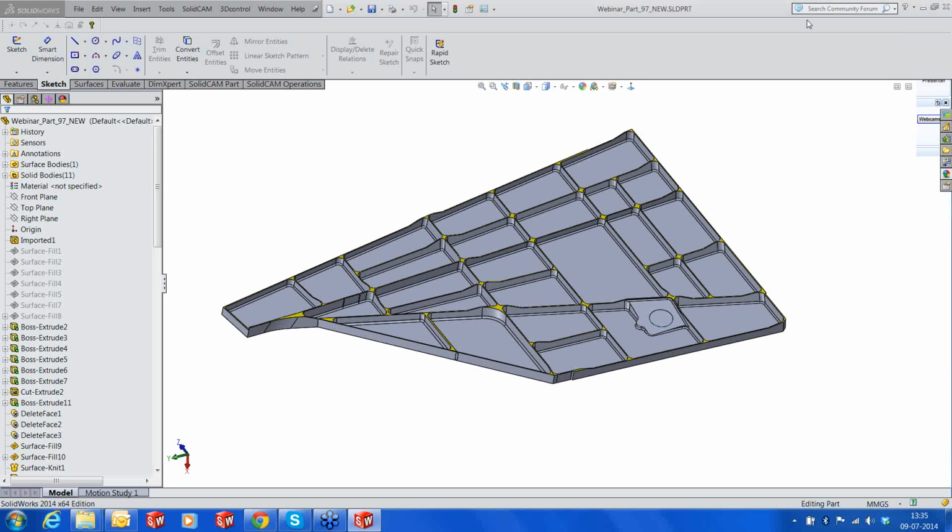so that you can get an idea on how we are going to hold this part first of all, because in an aerospace component you are not allowed to do it from casting or anything. It has to be from a single solid block. Now, a part like this, which is about 500-600 millimeter long, cannot be held in a vise. So you need some kind of a holding arrangement for this particular part. So we will create what we call lugs to hold this particular part, and we are going to hold that part.